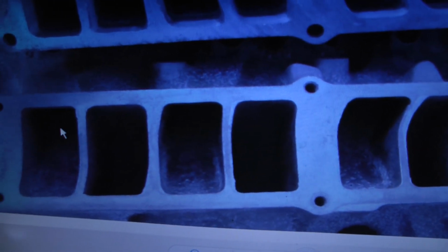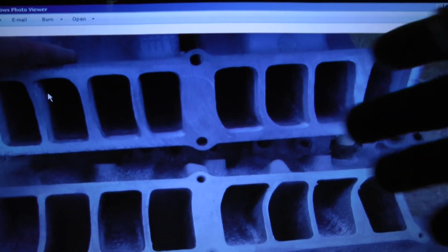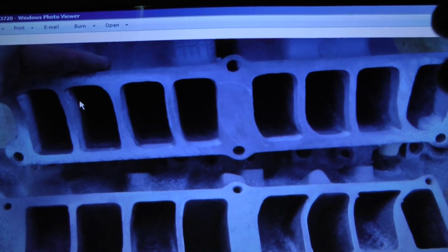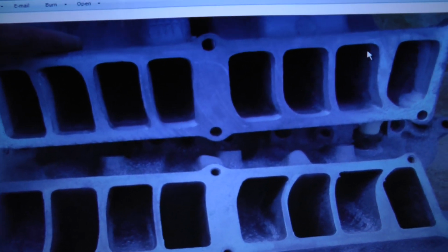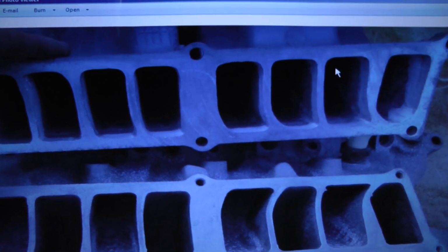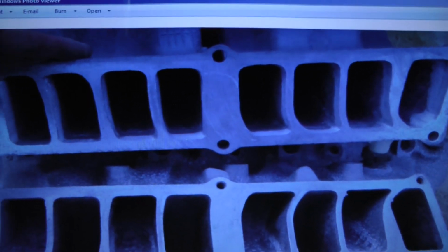The problem is, these areas are so thin right here. There's not really a gasket that can fit it, so this is pretty much all you can do with the dog legs. But now they're port matched, so it still opens up power flow. So the concept is from the throttle body through here, and then the intake ports are open, and then right into the intake bowl. So right from your foot on the gas pedal all the way to the intake bowl, everything is in harmony.